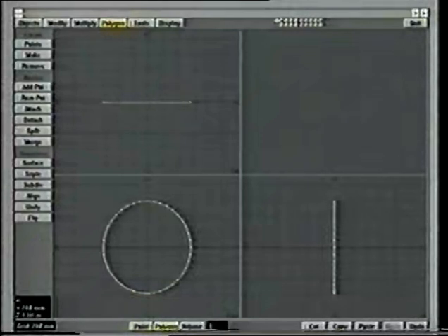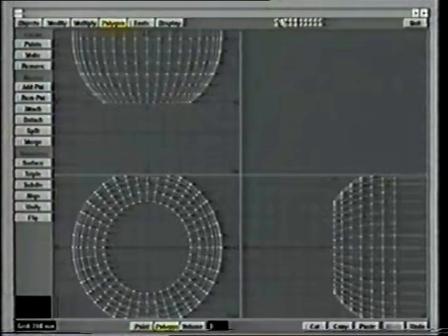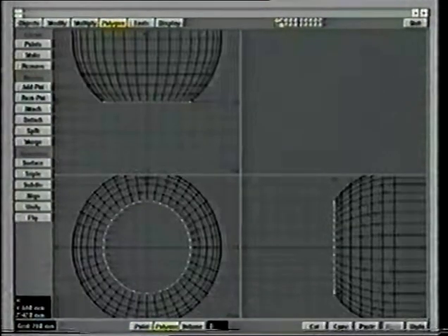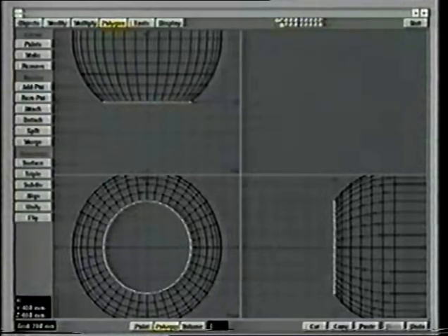So now we have the polygon. The polygon is now facing the wrong direction for me to extrude it in the minus z-axis. Let's put that in the background. See, I need to go in a minus direction, and as the polygon itself, the surface normal, is facing that way, what I extrude would be inside out if I did it in that direction.